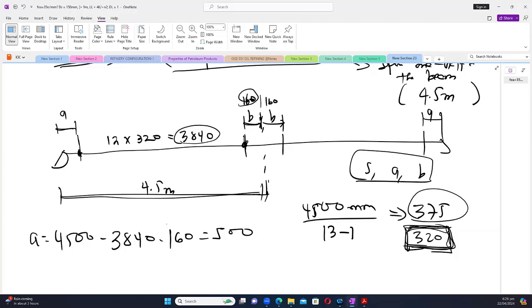Please, we do have a question. My good friend, ask your question again. So I was saying that when we're calculating for the number of studs, you said we should use the smaller value between the RS and RC. And I was asking why not by where the neutral axis lies. So you said you told them why in class.